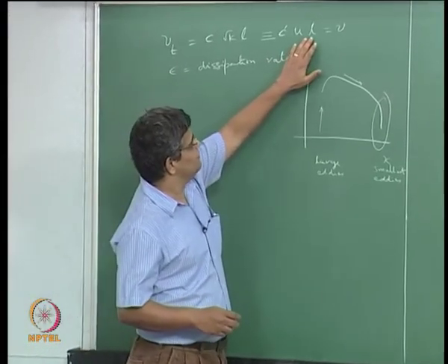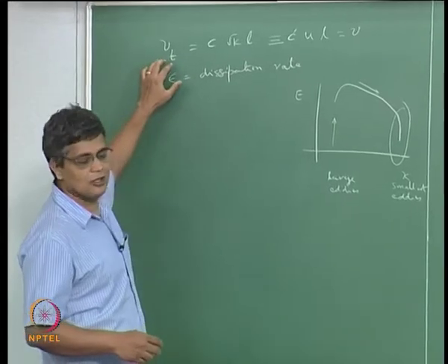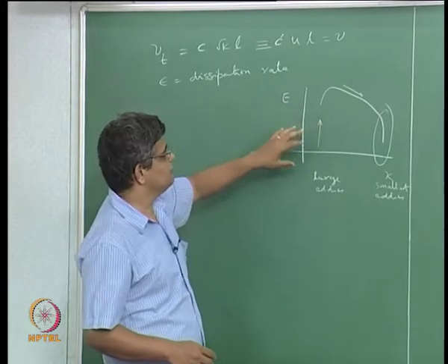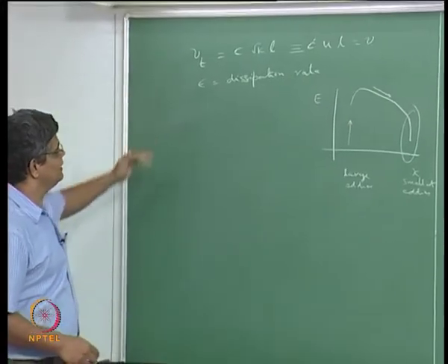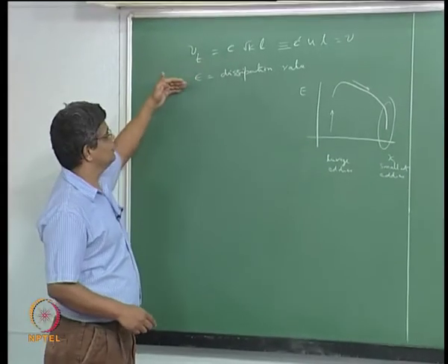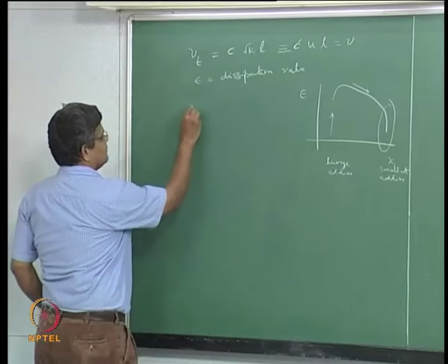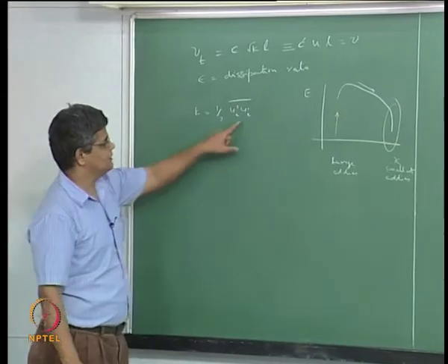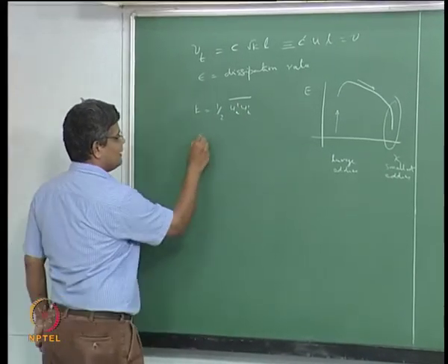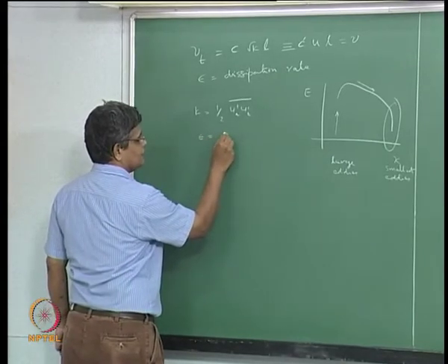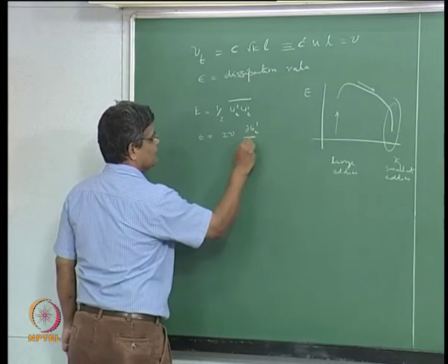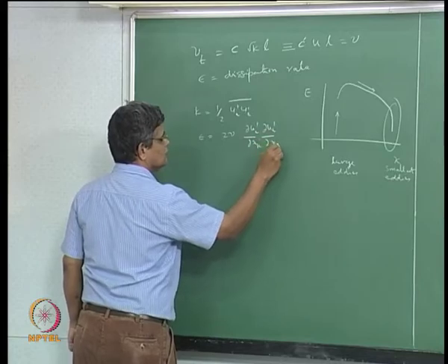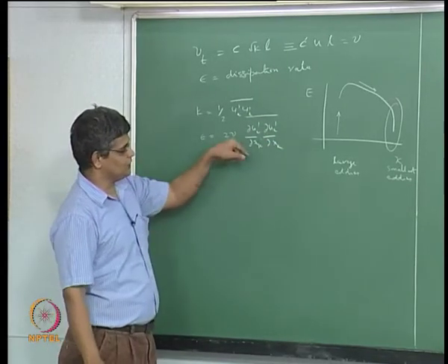Therefore, the length scale that appears here characterizing the turbulent viscosity is not dependent on the overall features of the flow, but it depends only purely on the turbulent quantities, and we have seen that we have here two quantities: k, which is defined as half of u_i prime bar, the sum of all the turbulent velocity fluctuations, and epsilon, which is defined as 2 nu (∂u_i'/∂x_k) over bar, squared. So this again is a positive quantity, square of these things.